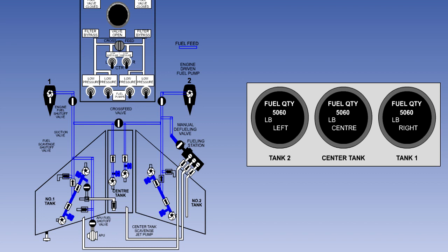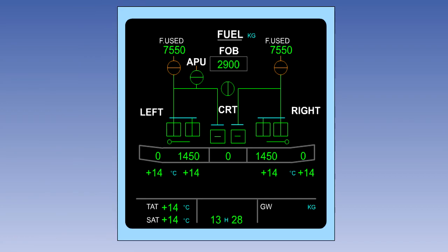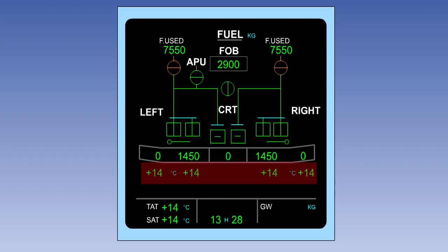On large aircraft, it is necessary to provide more information than this to the crew. On older aircraft types, the fuel control panel is usually in the form of a mimic diagram with flow bars and lights to indicate flow. More modern systems have electrically presented schematic displays. The diagram here shows a typical Airbus system display. Modern Boeing aircraft have similar displays. The temperature of the fuel in each tank is shown here. This is important information for monitoring the system for fuel icing or fuel waxing.